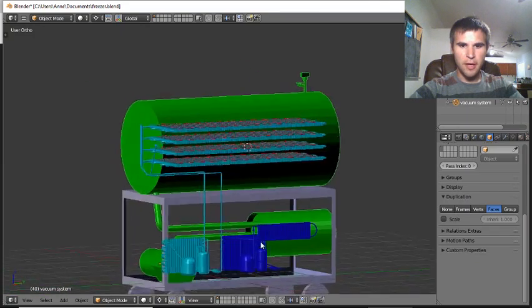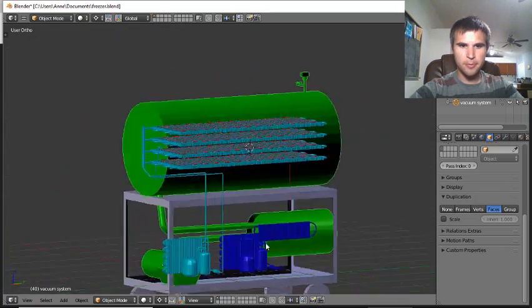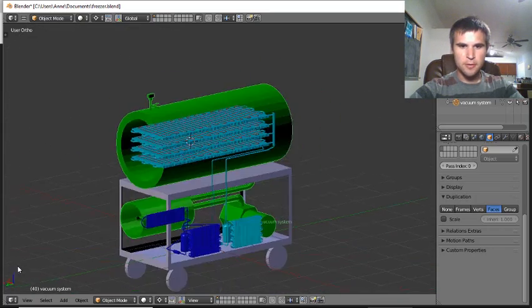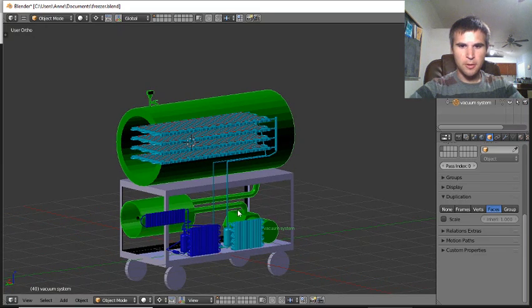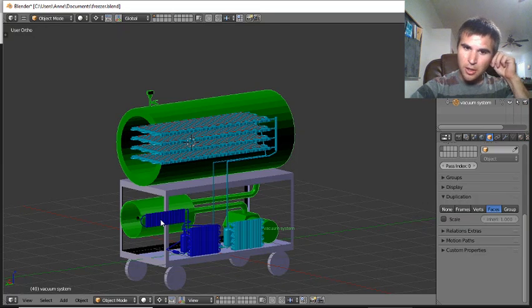I've got it drawn in here that the vacuum system pulls first through the cold trap and then up into the vacuum. See, get a good angle of that. So the vacuum pump here would pull through the cold trap, which would just be another tank. It's all going to be under the same exact vacuum pressure. So I think a round propane tank that you purchased, either just a regular 5-gallon propane tank, or maybe one of the tall boys that's the same diameter but a little bit taller, I think they're like 10 gallon ones, and then we just cut the end off, drill a couple of holes and weld our pipes onto it.